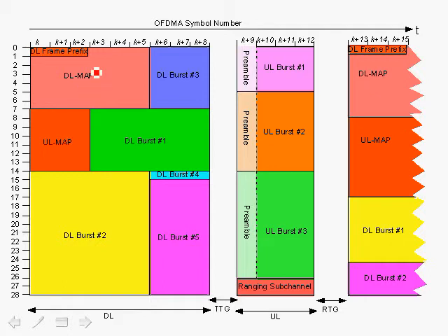And of course the intention is that the subscriber stations that receive this information, when they decode the downlink frame prefix, will know what the rate is for the downlink map and are able then to decode it properly.